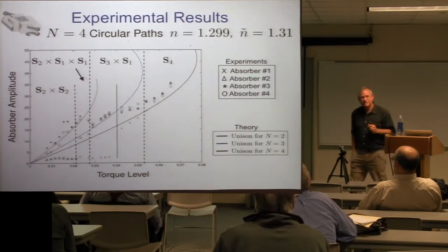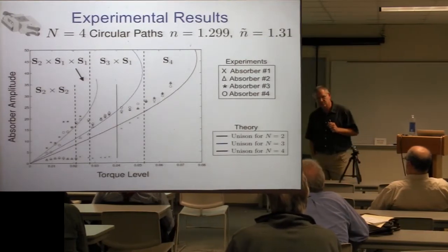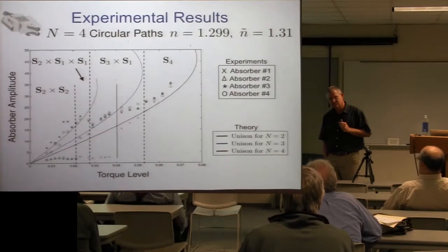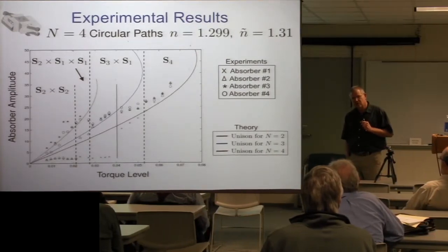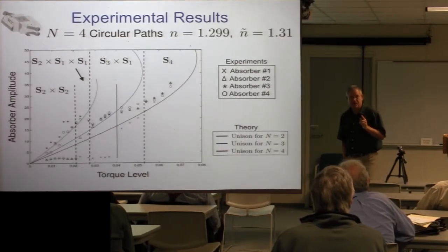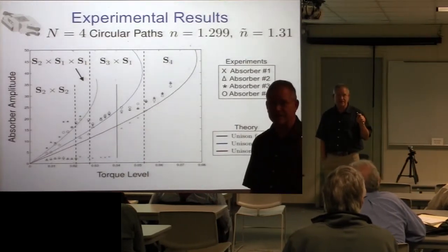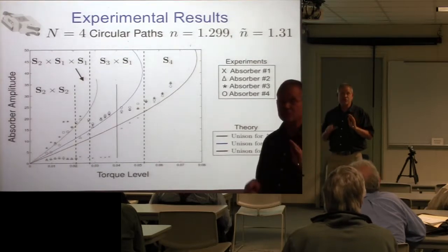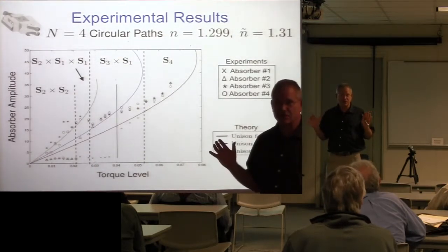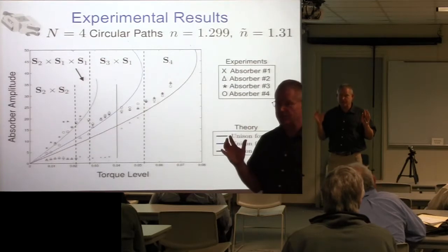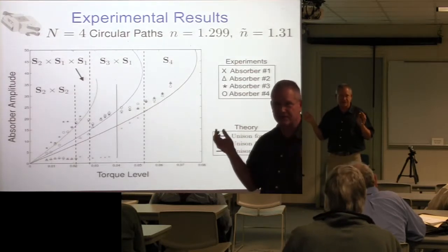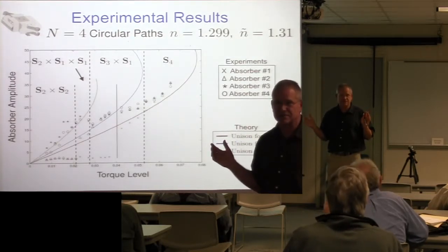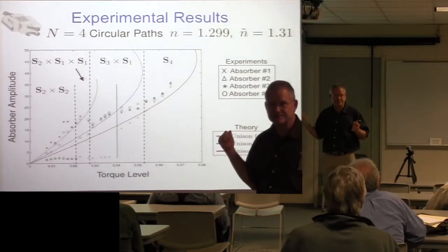And n equals 4 absorbers has more resonant terms than the normal form. Are those included in your model? So you're talking about the normal form for the bifurcation and all that? Okay, so, John, these equations are a nightmare. What we do in the average equations is keep whatever comes out of the averaging and just solve the average equations. We don't try to do any transformation to get rid of any terms. So whatever was in the full equations and survives the averaging is in there.